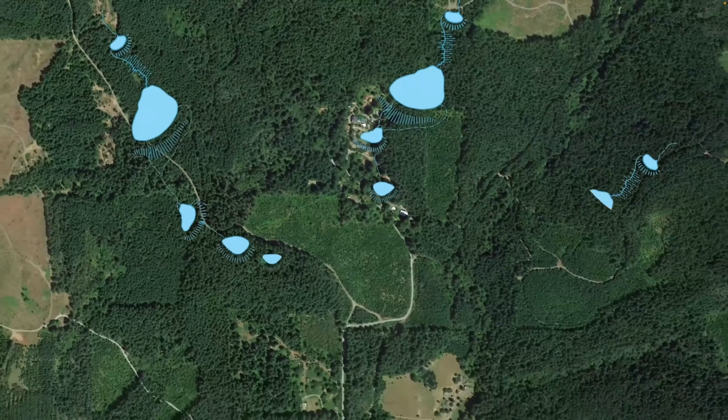A cross-sectional diagram would show the inside slope of the dam, the outside slope of the dam, the width of the crest of the dam. It would show the back slopes of the dam and what those look like. It would also illustrate whether or not there's going to be internal terracing in order to do aquaculture and create different microclimates within the pond, and the depth.